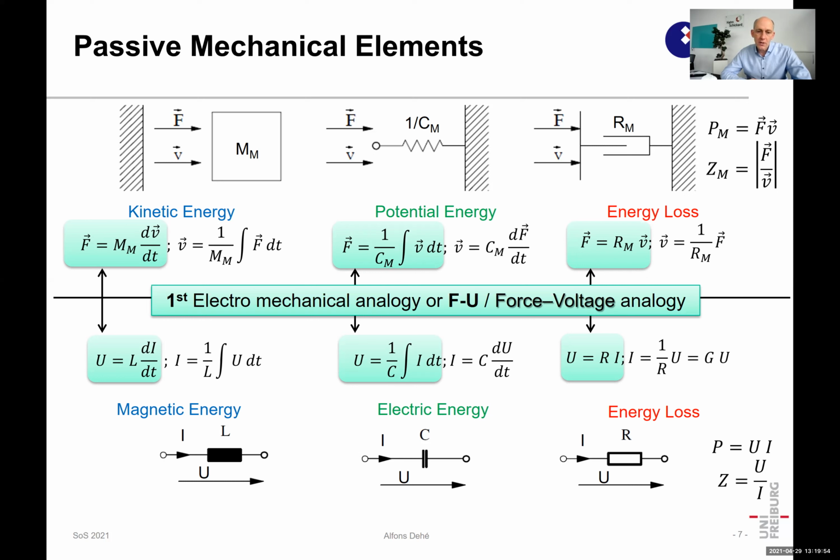Force is analogous to the voltage in a circuit, and velocity proportional to current. We call this the first electromechanical analogy, the force-voltage analogy. And this helps us finally to describe mechanical circuits and solve them in the electrical domain.